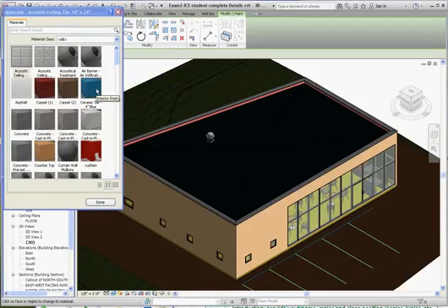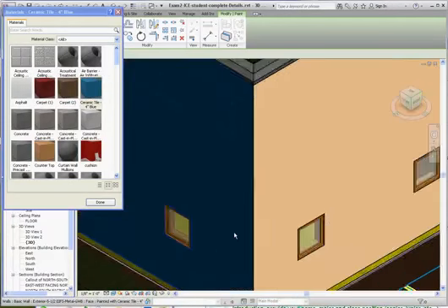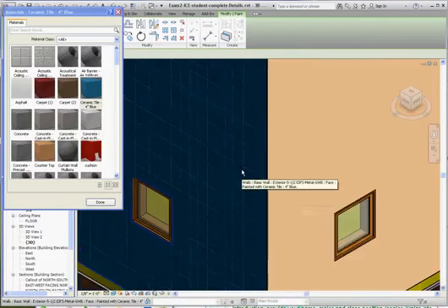It comes with the stock item here, which is blue color. We just click on that. We want to make sure it's selected in there so it's blue. And since our Paint tool is already selected off of our Modify tab and our ribbon, we just have to click on it. Click on that wall, and now it's a blue tile. We'll zoom in on it, and you can see how that changes.